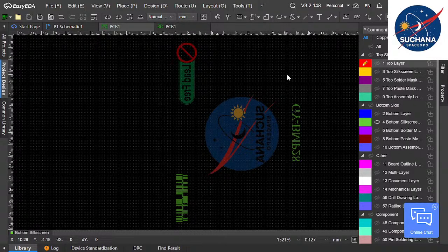If you check it, then you can place a colorful image, or else it will be downscaled into something like a black and white or grayscale format. So if you want a colorful silk screen layer, check the option, so that there will be no mutation of the image. As it is, it will get placed in the layout manager.